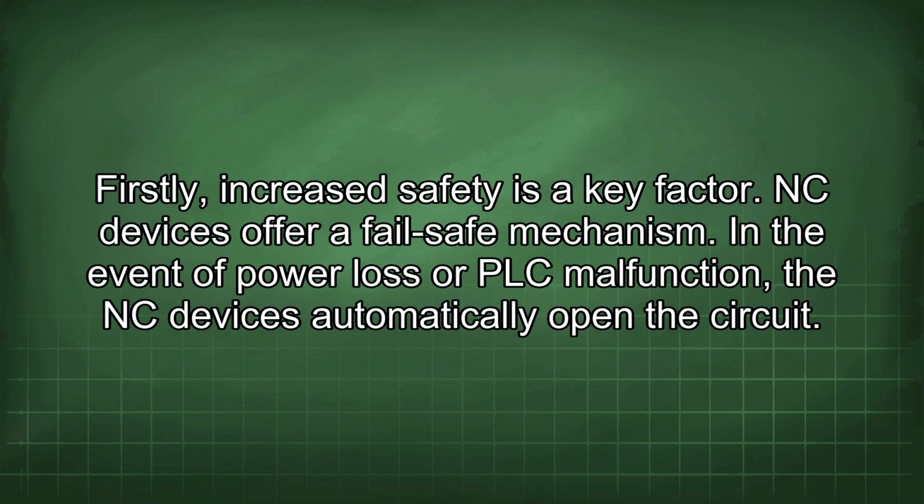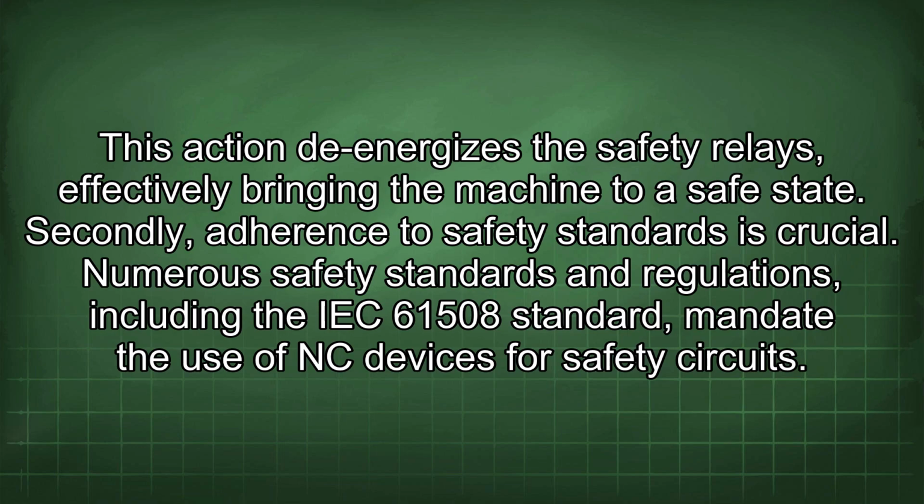Firstly, increased safety is a key factor. NC devices offer a fail-safe mechanism. In the event of power loss or PLC malfunction, the NC devices automatically open the circuit. This action energizes the safety relays, effectively bringing the machine to a safe state.